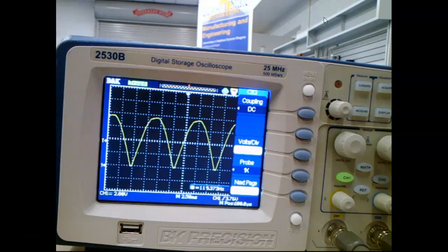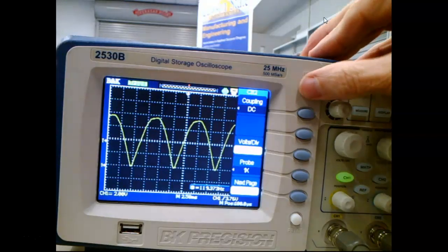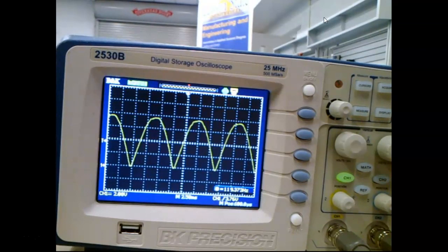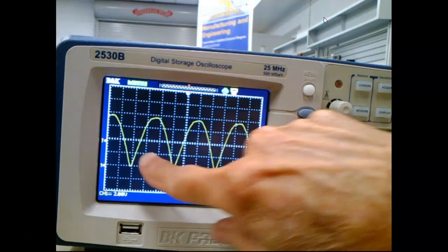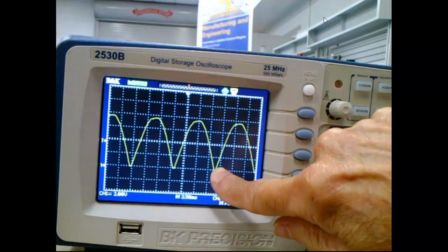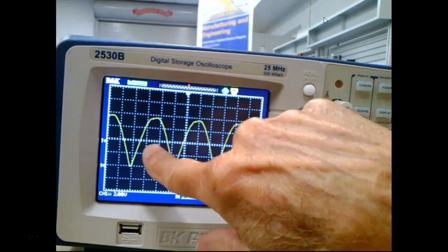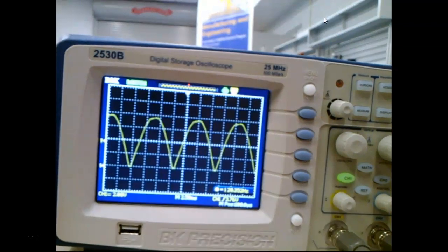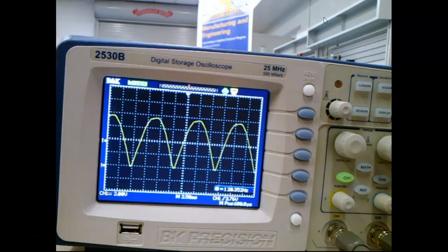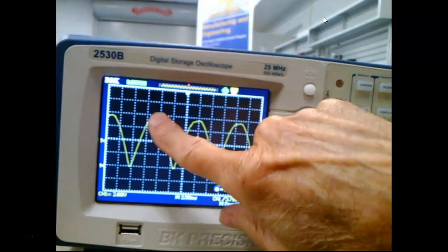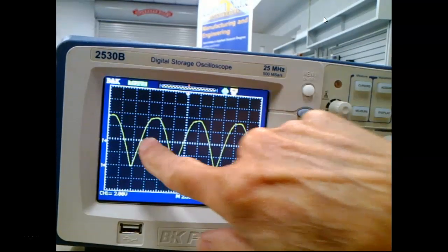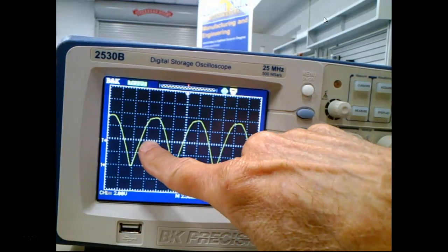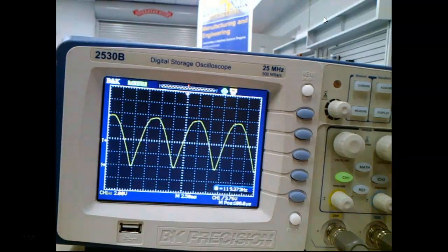So what is a cycle? It's the number of repetitions per second. So here, this might be the positive alternation, this might be the negative alternation, so I'm getting 2 cycles for every one AC input cycle. So this would be 1 cycle right here, so that'd be 8.33 milliseconds, would be 120 cycles per second. Put 60 cycles in. And this is full wave.